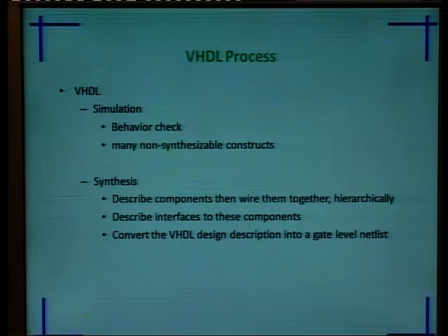Next is the VHDL process. VHDL process is basically divided into two parts. One is the simulation part, and the other is the synthesis part. In the simulation part, we verify its behavioral function, as I have given an example of a simple adder. If we have two numbers, are we getting the sum at the output or not? That behavior has to be verified for all the combinational circuits, and then it may be synthesizable or non-synthesizable.